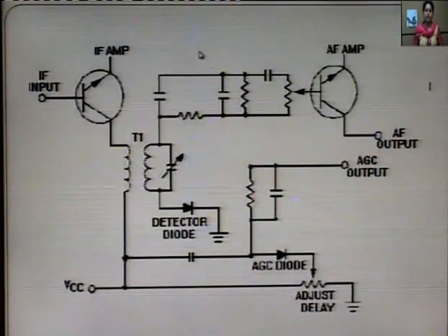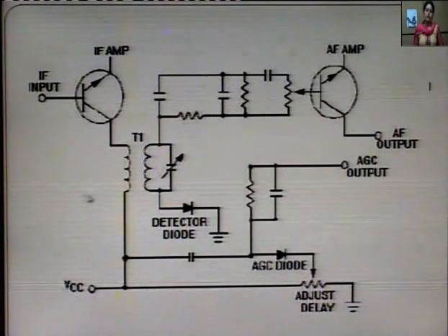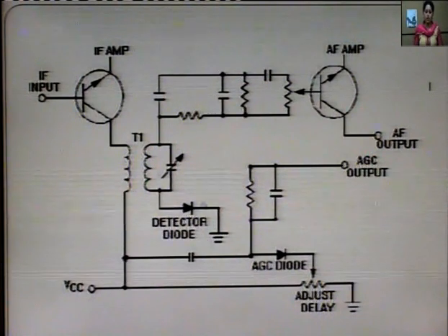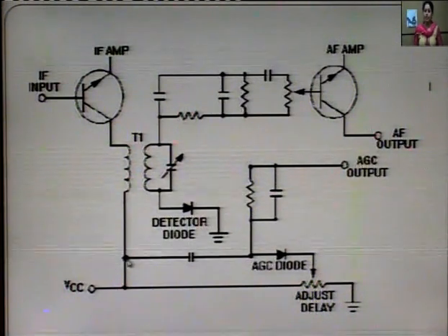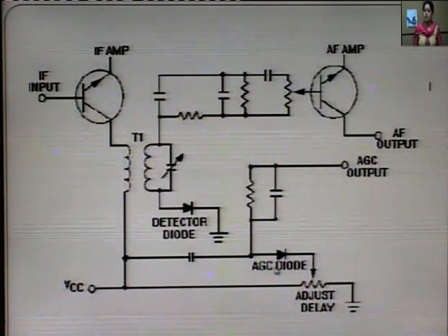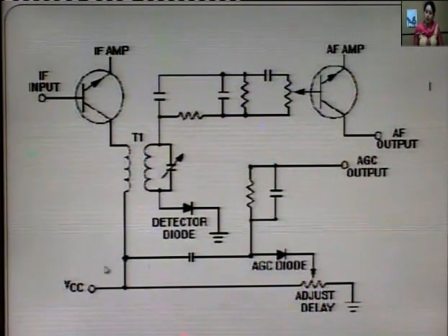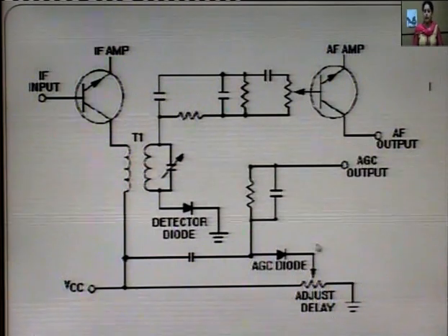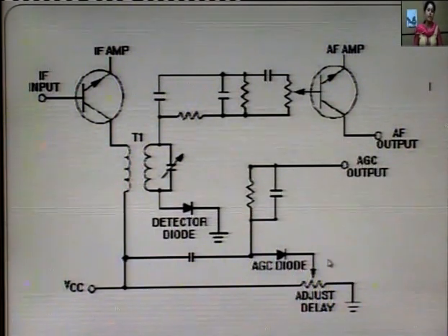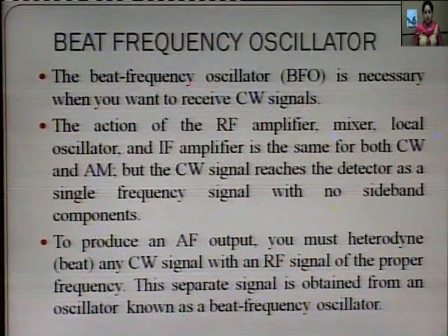Here again the block diagram of a practical detector stage is given. You are having two diodes, one is the detector diode and one is the AGC diode. It is connected to this coupling capacitor. When a predetermined level is not achieved, your AGC output is 0, your diode is not working for the weaker signals. But after a predetermined level is achieved, your diode is forward biased. At the output you are having a constant voltage, so reduction in gain is provided for your stronger signals.